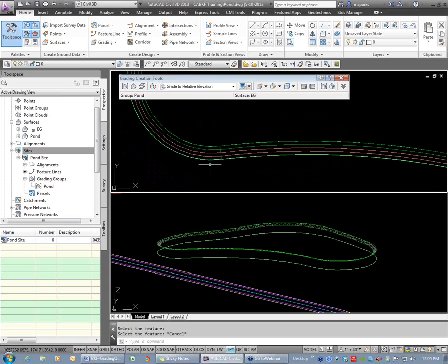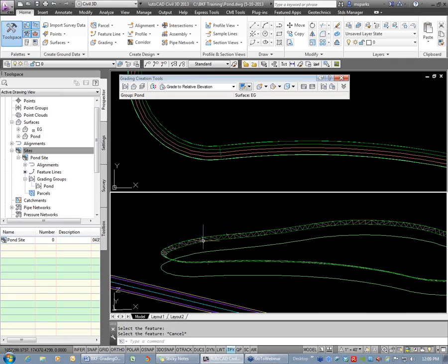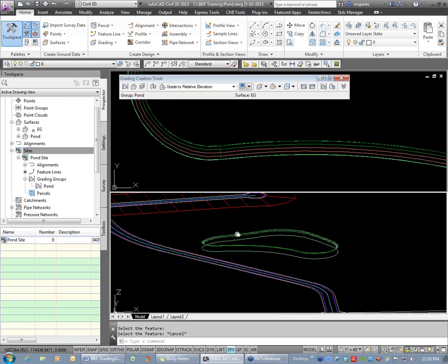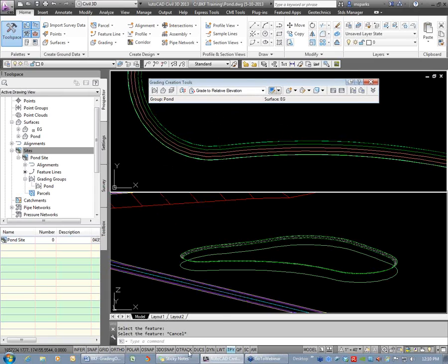So you'll see here, I'll hit escape to get out. You'll notice that because I checked the box that said automatic surface creation, the contours come in and the surface is automatically there as well. If you're not seeing it in 3D, a lot of times instead of minus 4, I might put in 4, which would go the wrong direction. So I can immediately see that in 3D. That's why I like to have the 2D and 3D realm here.